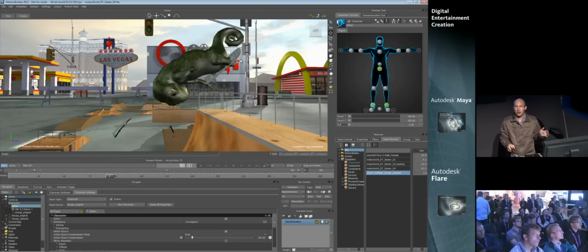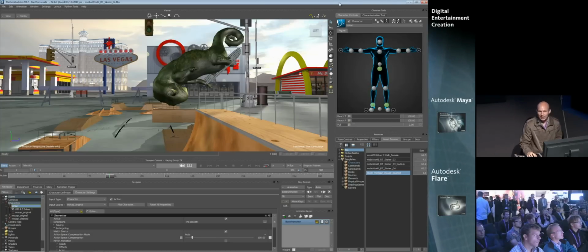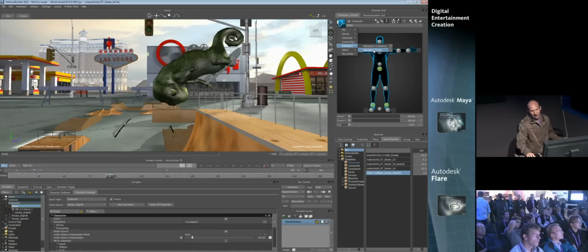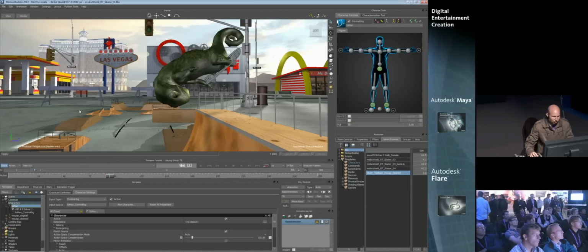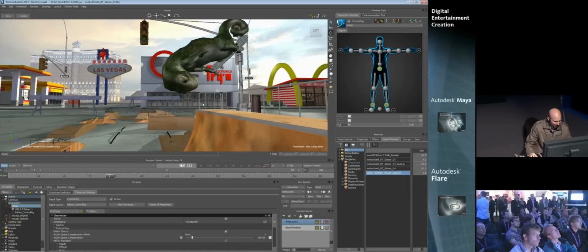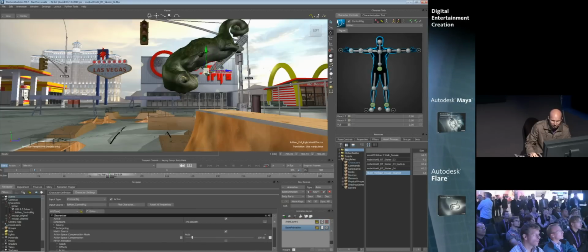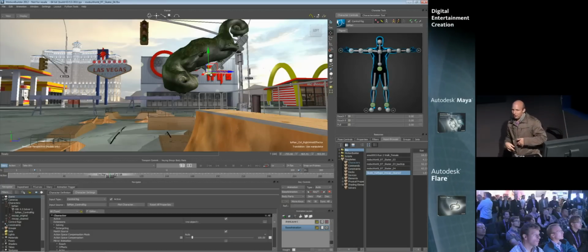So what we want to do is transfer this information onto that control rig, that HIK solver that we talked about earlier. This is a very fast, easy process inside of Motion Builder. All we're going to do is say plot or bake. So we'll put that information on that control rig, and now I have the ability to begin layering animation on top of that. So we'll grab a new animation layer, and what I want to do is reposition that hand. If we were to jump down to our hand here and start to reposition that, I could start keyframing offsets on top of this, which would be good for some situations. But for this guy, I know I want that hand to stick to that skateboard.